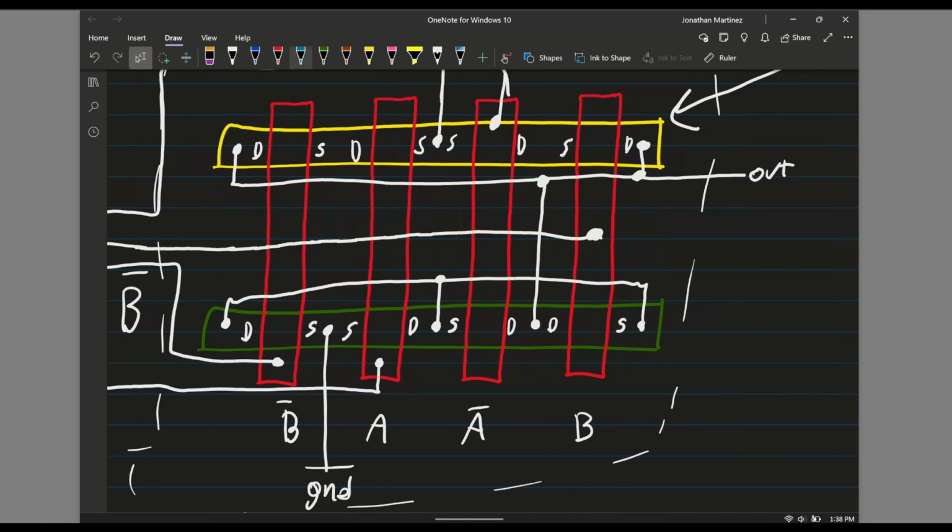And there we can see it. I'm going to go ahead and draw with a blue line here. Basically it's a single node, but it connects 4 components. All right. So right here we are up to 3 components now, and then we go to the final component. Now we are at 4. So that one line connects the 4 NMOS transistors. And just to reiterate the point, all NMOS transistors are located here.